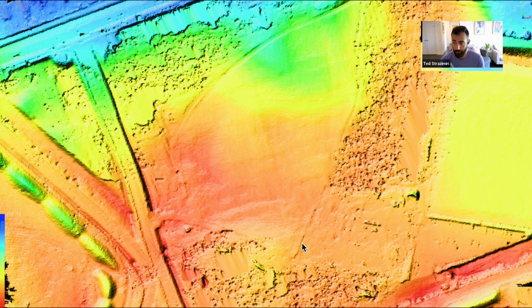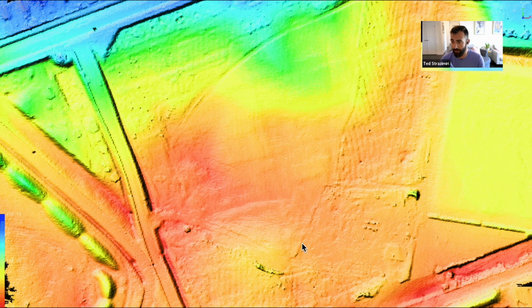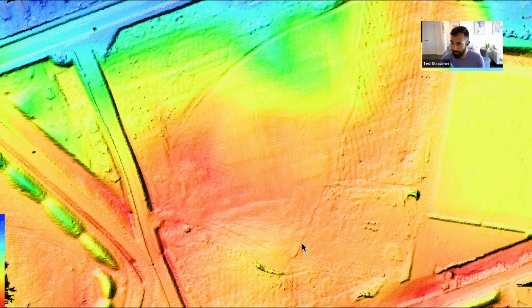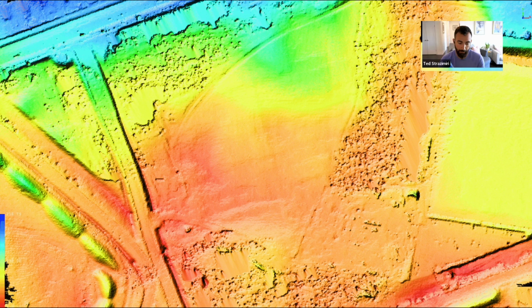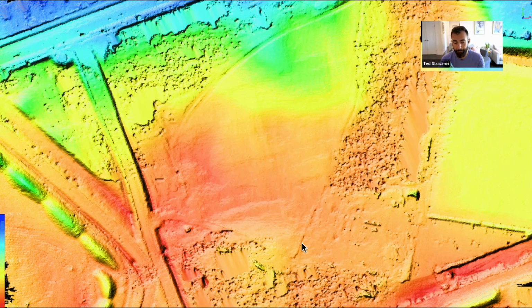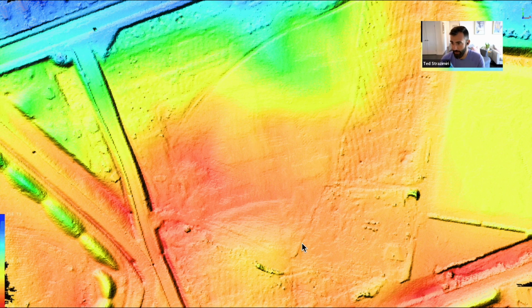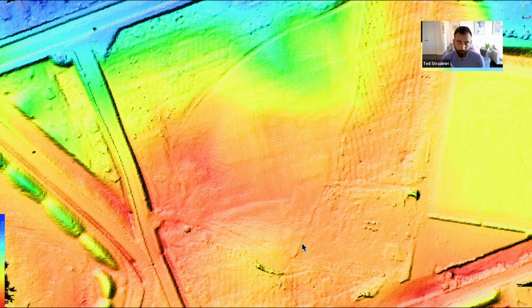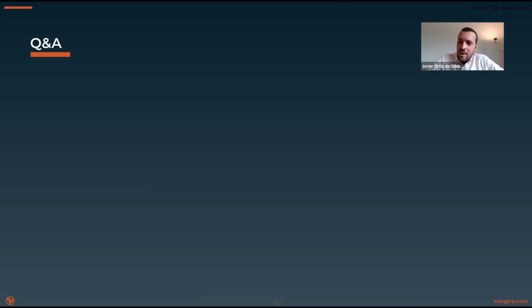whole point of this is that we know that trajectory is very accurate to begin with, and that's what you're paying for. You're paying for that hardware inside of that sensor, the IMU, and the GNSS receiver inside of there to be of the highest grade and the highest quality. And that is essentially what determines the accuracy. And then the laser determines your efficiency, right? You can cover huge amounts of area, regardless of the terrain cover, and get really good, really consistent data as well.